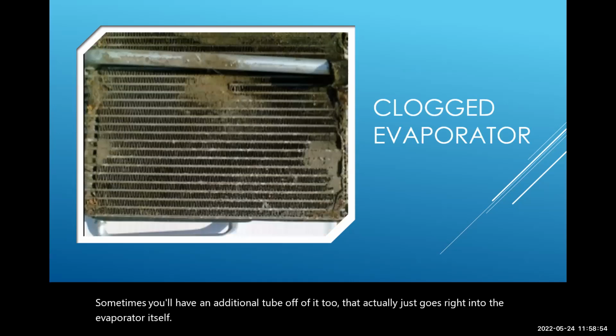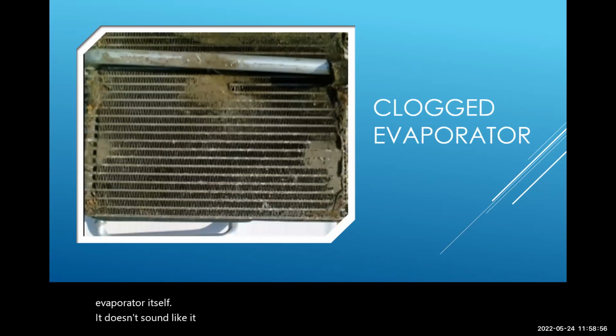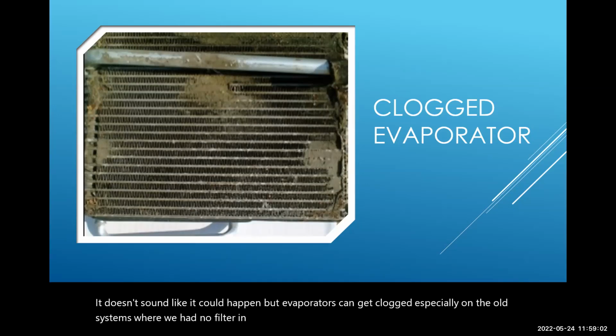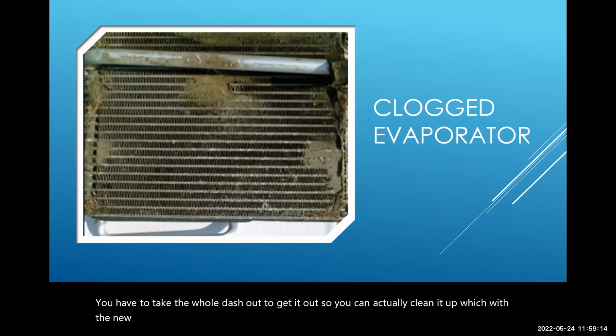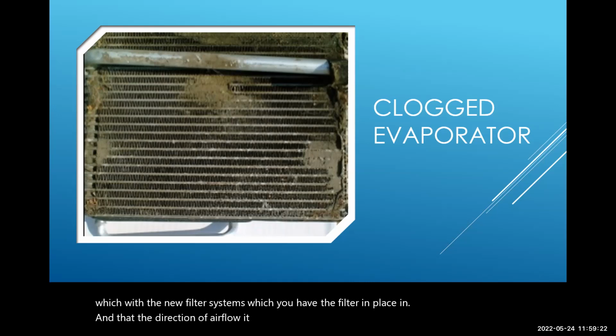It doesn't sound like it could happen, but the evaporators can get clogged, especially on the old systems where we had no filter in place. These can get debris in place, and it is a pain, you have to take the whole dash out to get it out so you can clean it up. With the new systems, which have the filter in place in the direction of airflow, it won't be as bad.